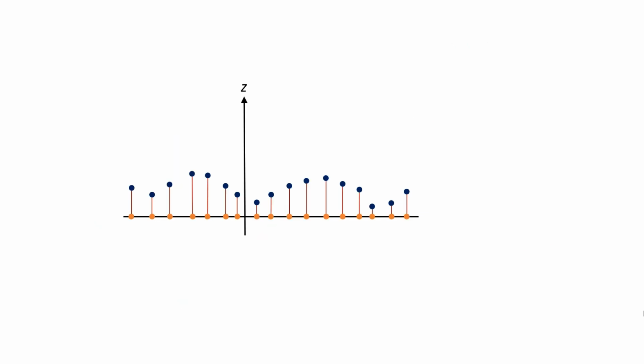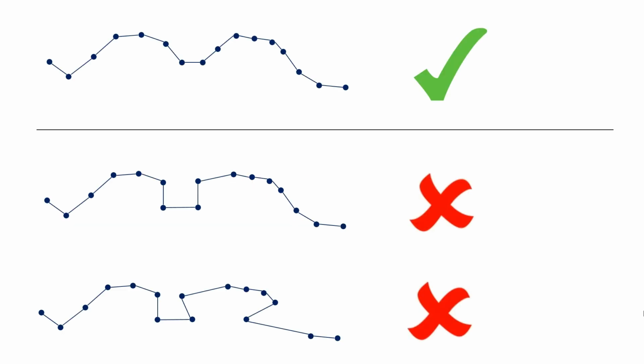Analogously, when generating a triangular mesh with a planar geometry, the input 3D points are projected on the X and Y plane. So you will be able to correctly obtain the mesh only for surfaces that do not have overhangs in Z.